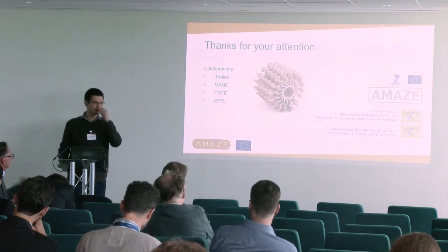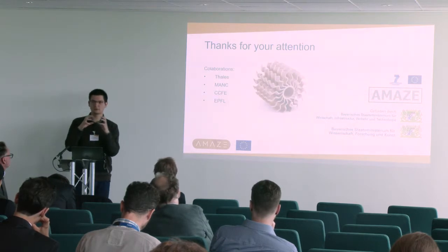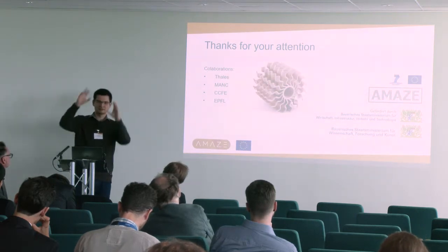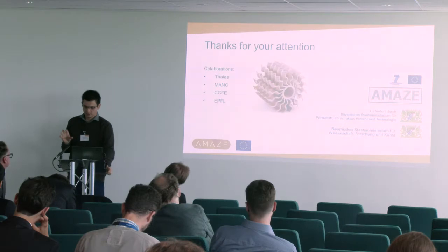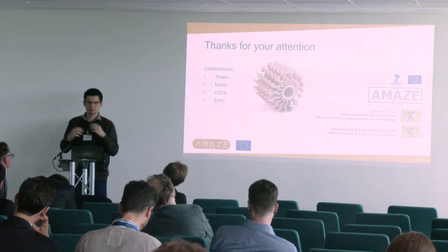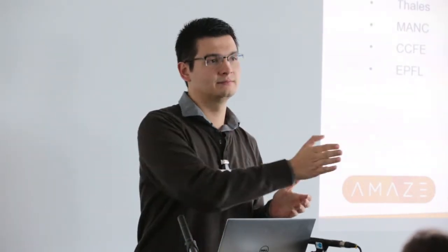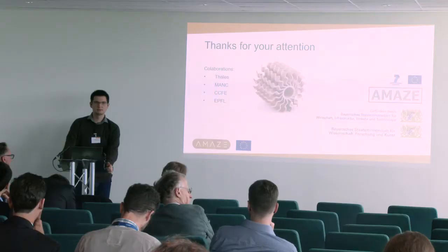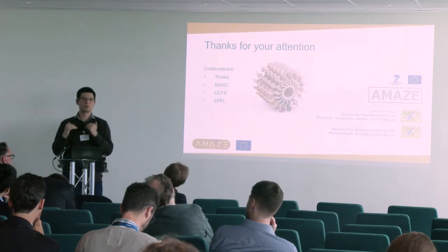One second application that we also worked on, and still work on, is in the energy sector. You can use it as an absorber for sunlight. It gets under heat stress: a cloud comes, it cools down, the cloud goes away, it heats up, and you can minimize the stress by simply changing the structure. Right now they're using normal structures, and if you use an auxetic structure, you minimize the stress on the whole structure, and the lifetime simply gets longer. So this is also one application that we work on right now. But yes, anywhere where you want this Poisson ratio below 0.